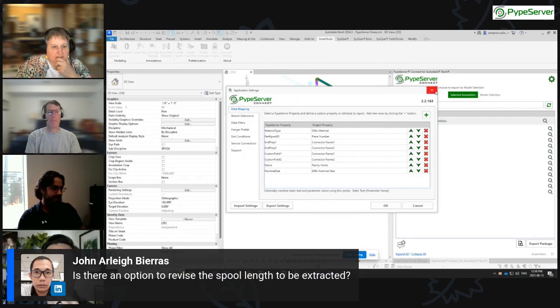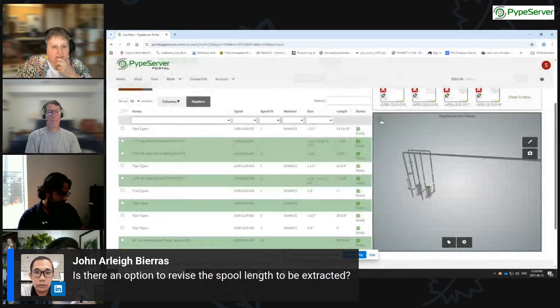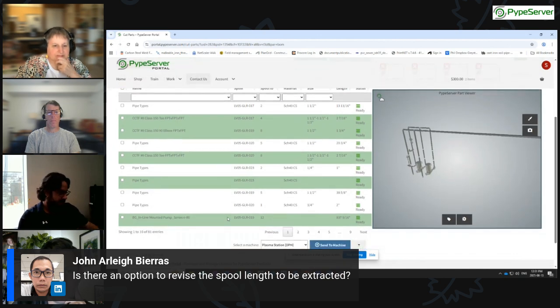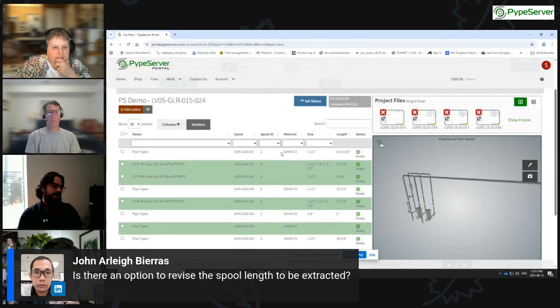So by doing that, back on this screen, it's reporting schedule 40 carbon steel. This is how we know it. Now we can nest everything through all of that material. So if I had copper here too, we can go and cut through schedule 40. We can cut through all of our copper because we've set it up that way. Same thing with the sizes. We've made it more applicable for sizing, so the way that we actually order things.